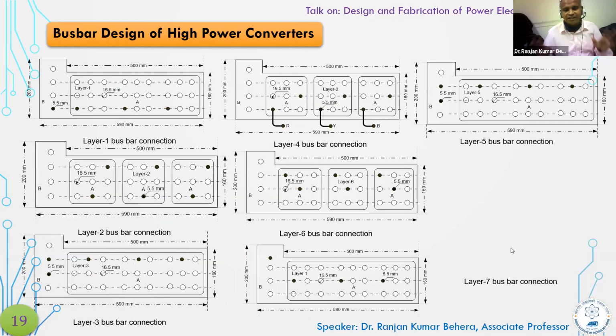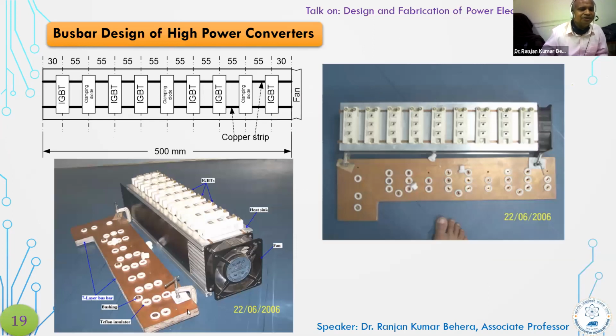And you can see that each bus bar, here we designed bus bar number 1. I have put this black color, meaning the upper bus, one bus is connected to only this black color. This one is also connected, then this one is connected, and the positive bus is connected. And the second bus is connected only to this one and this one, this one and this one. Like that, all these bus structures are connected like this, and this is the RYB output connection. After designing this bus structure, we designed the complete unit.